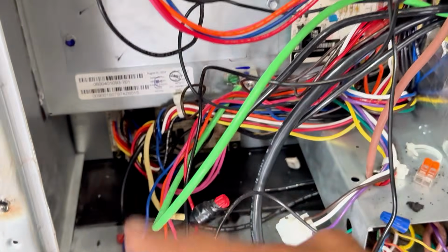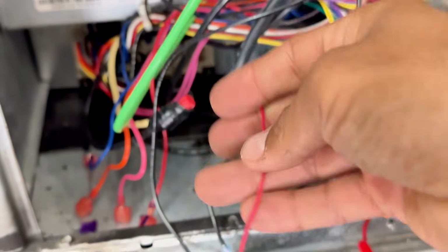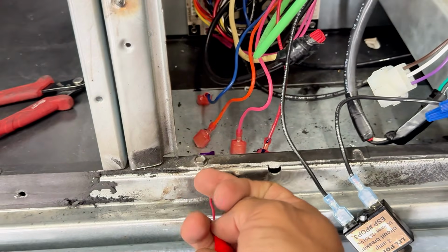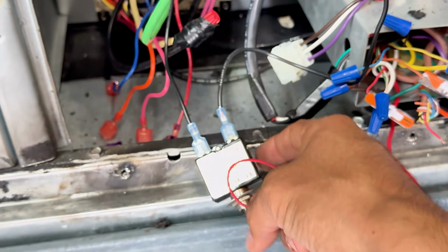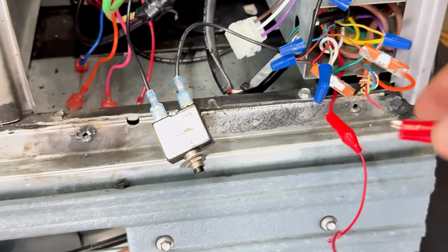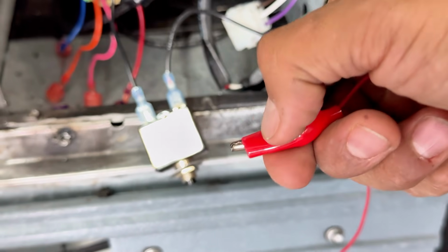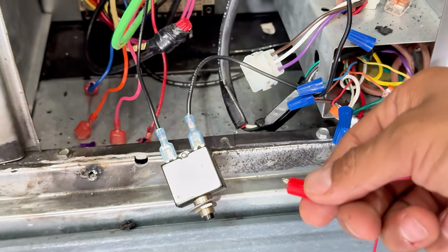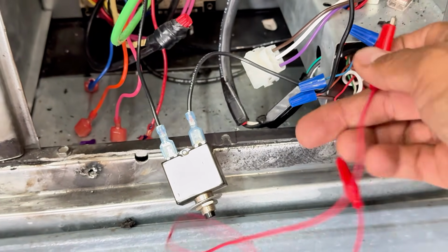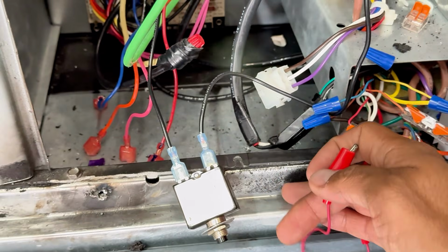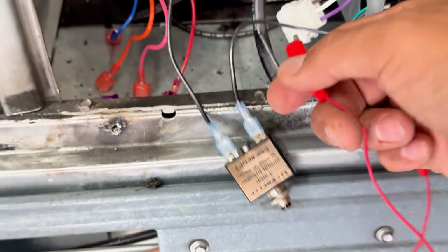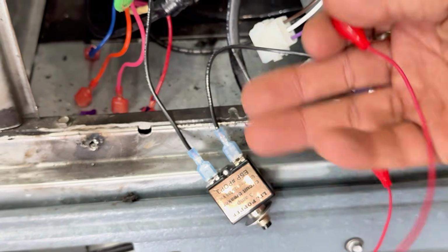They're fighting. So that 24 volts travels through my system. Due to vibration, it can expose the copper and then it can be touching the metal. And if that happens and it pops the fuse, well, good, it did its job. If you don't have that common grounded, we run into more issues. You get like 18, 13 volts. You get these weird voltage drops because now the common is not grounded, but the hot is stripped and touching the metal. You're going to create resistance. You're going to have these weird voltage drops.